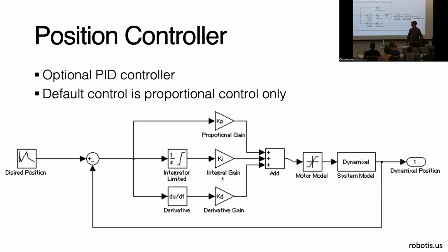All right, so to control its position, we're running this controller internal to the motor. It's looking at the desired position as a command that you send it. It's looking at the actual position of the motor from some sensor, and then it's running a PID loop inside to determine how to drive that motor to minimize that error.